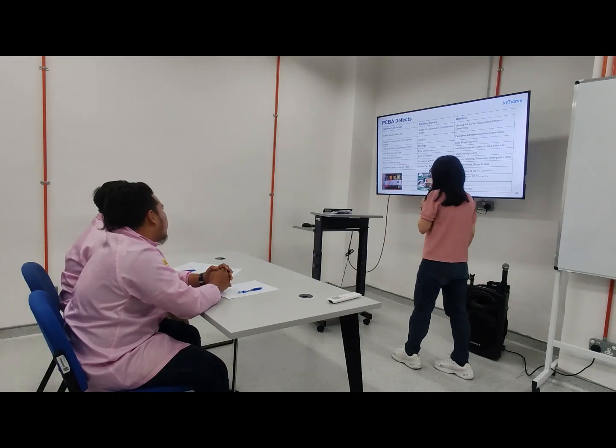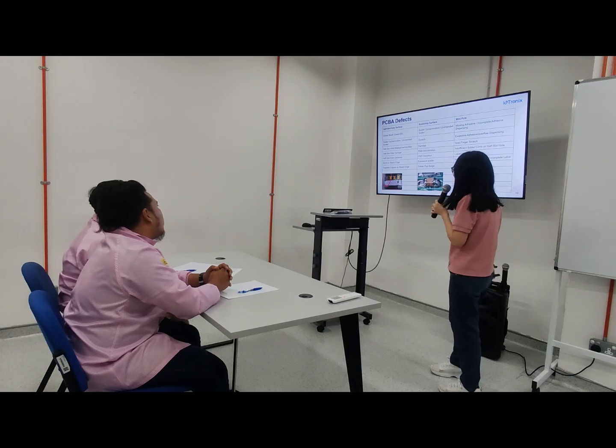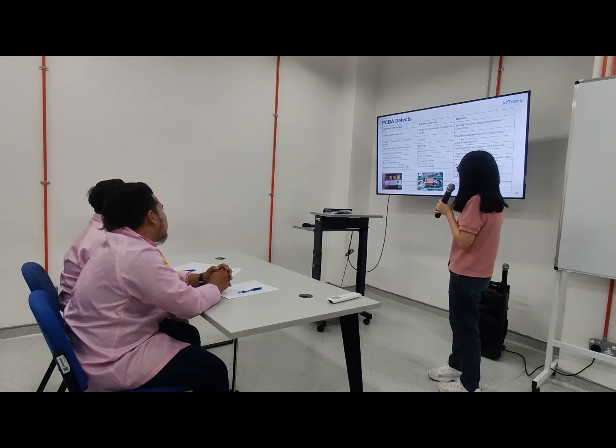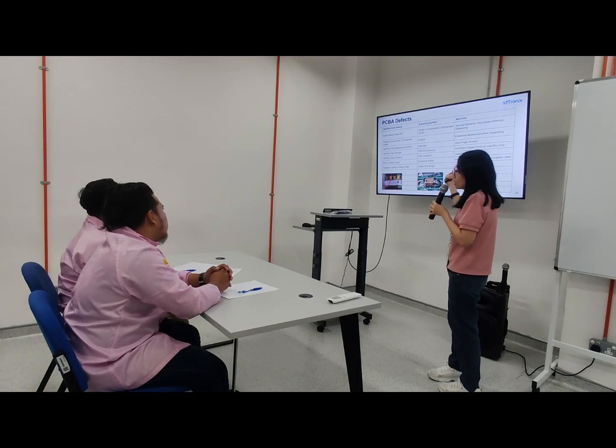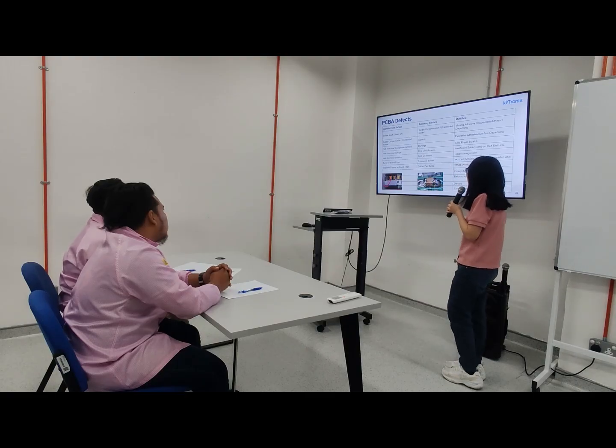Half slot surface, normally we have solder contamination. So the mask and solder contamination, the half slot misaligned or shifted or damaged, oxidation, burrs on the board edge, exposed copper. So during surface, normally we have the solder contamination also, scratches, damage, pad discoloration, oxidation, excessive solder, example, excessive solder, and solder pad.